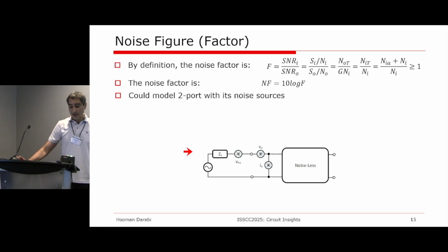So let's revisit now the noise figure definition. The noise factor is, in linear fashion, the ratio of signal-to-noise ratios. And if you take 10 log of that, that will give you noise figure, which you saw earlier. The ratio of the signals is basically the gain, G. And this could be less than 1. Doesn't have to be always an amplifier.